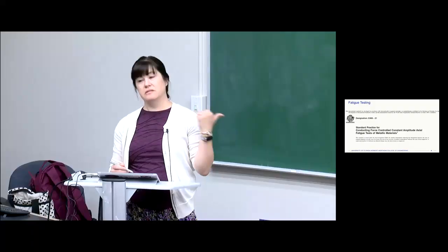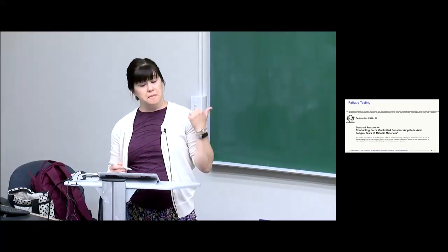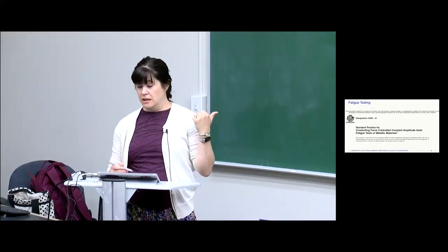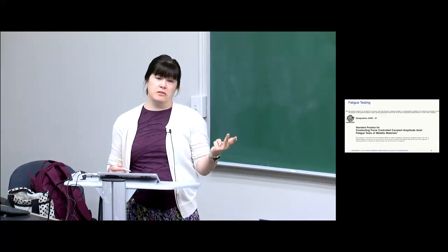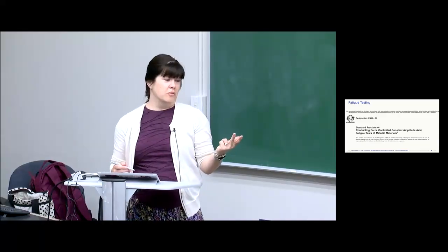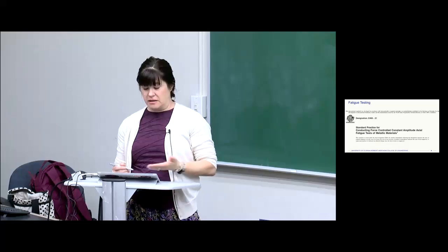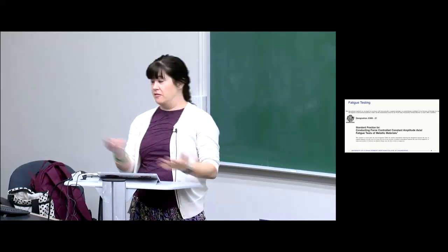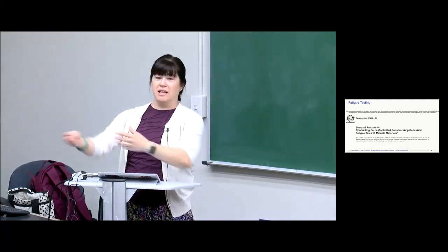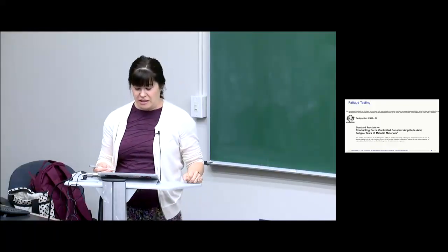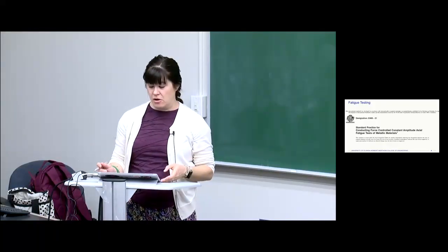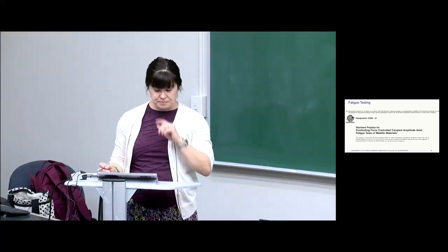And so that's why I wanted to present this to you, so that you would have an idea of what is the scope of these types of standards, what is the level of detail of things that are specified, and then also maybe what things are left out. So when you are looking at this kind of data, you're asking a fellow engineer, how did you collect this data? Did you follow ASTM E466, right? Things like that, you can check up on that and know that that was done correctly.